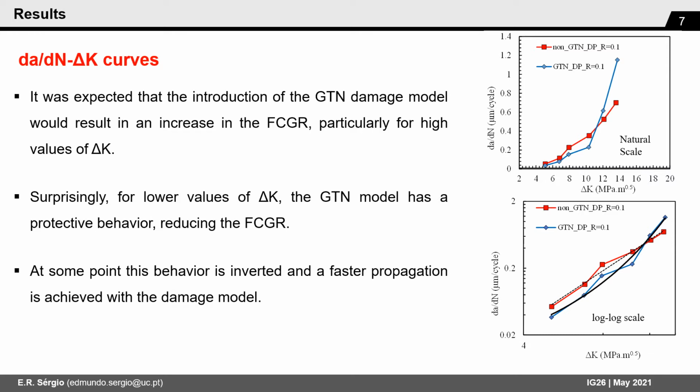In log-log scales, without GTN, the da/dN-ΔK curve has an approximately linear behavior. With GTN, this trend is also followed, but only until the protection given by the damage model is reverted in a faster propagation.